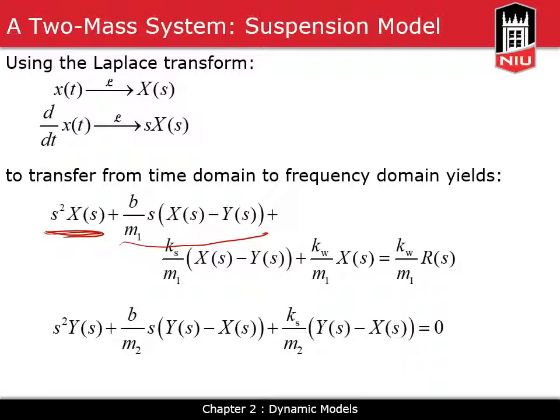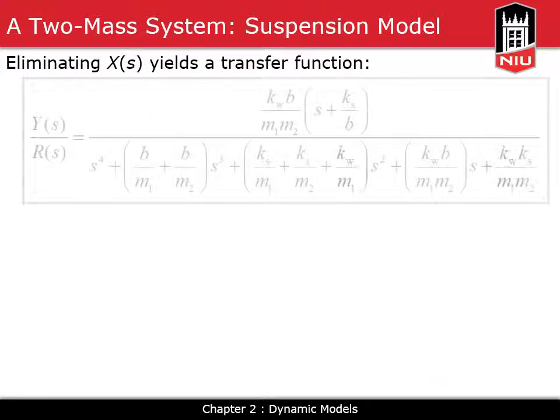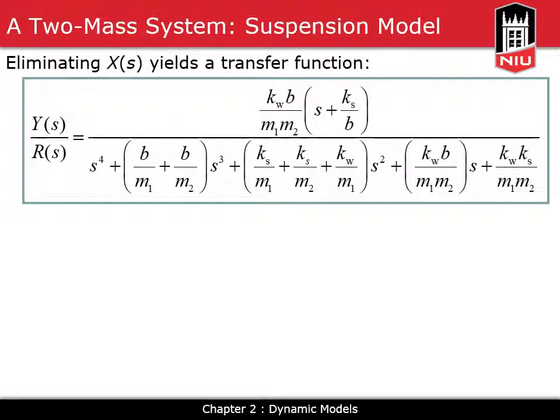Now we have everything in the S domain. So here it will be easier to find x from one equation and replace it in the other equation. Whereas with the differential equations in the previous slide, we cannot really do that because they are not algebraic equations. So here, we will find x from one equation and replace it in the other. We will get an equation that has only y and r as its variables. So that is where we will be able to find y over r.